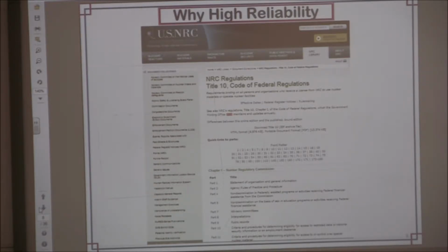So they actually asked the president of the country at the time, Jimmy Carter, to go say it's safe to be there. They weren't actually certain that the place was not going to blow up at any point in time. So they added the requirement that you include hydrogen monitors inside containment just in the event of a meltdown. They called a lot of the changes post-TMI modifications. Those were requirements from lessons learned.